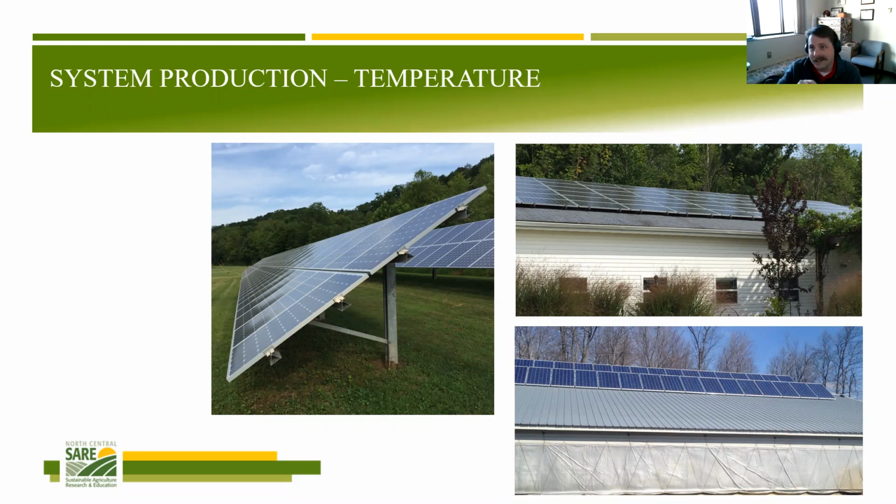Now this, luckily, it's not a huge amount, but it is something that when we model, we take into account, whether it's on a roof or out in the open. Because if it's on this roof on the right here, it's going to get warmer than if it's out in the open where there's a lot more airflow. And so they're going to take that into account, and it's going to produce less for the same size and tilt, slightly less. Also, cold temperatures, they're more efficient.